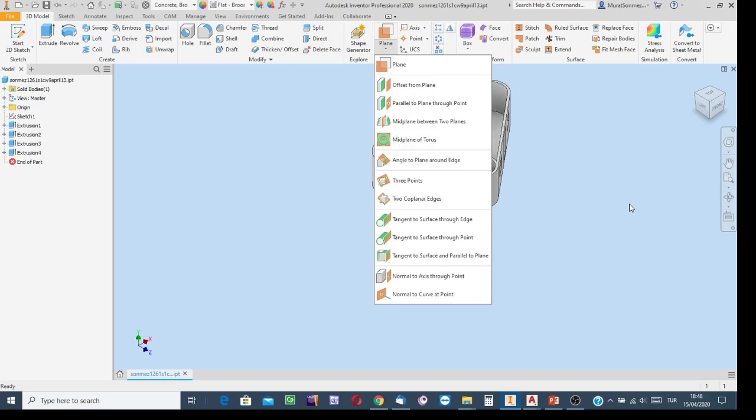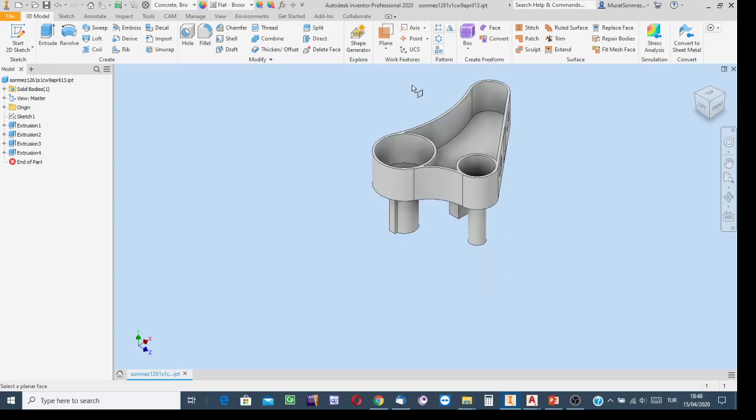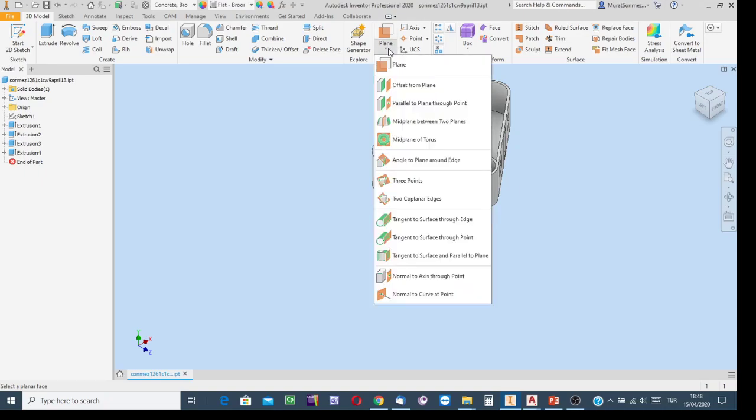Here, the suitable option to have a work plane, the necessary flat plane, to select from this list is the offset from plane option. And then I started the process and the system asked me, sure, as it is implied from here, you see in the schematic figure for this option, there are two planes, one of them green, the other one brownish or orange colored.